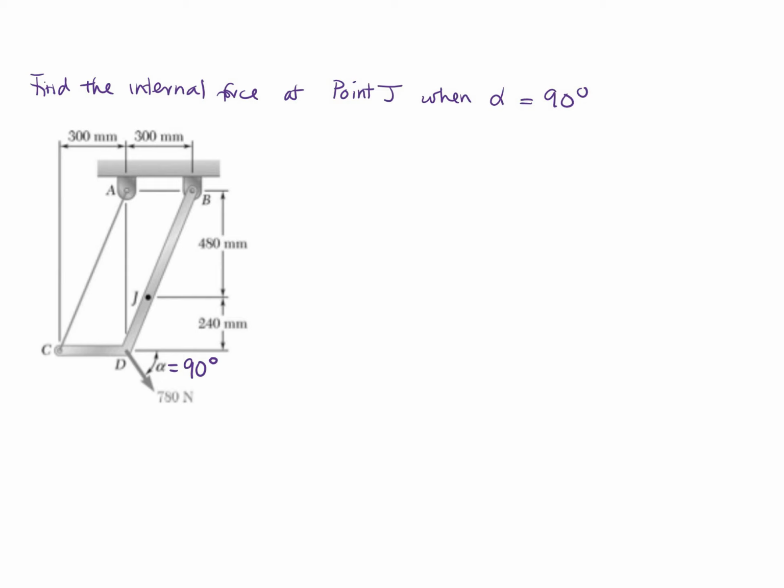So to get started, remember what we want to do is find our reactions, right? So we're going to label all external loads, which I've been doing, and hopefully you'll be learning from that. I'll actually go ahead and change this direction. So we have By and Bx. And then if you recognize AC is just a cable, which means it can be represented as a force, and that we'll call that FAC. And we also know that 780 is another force over here.